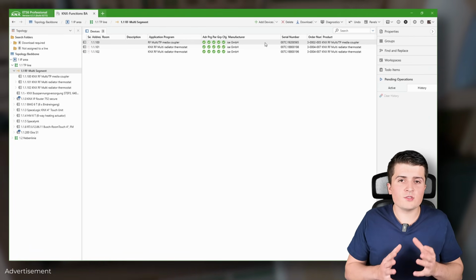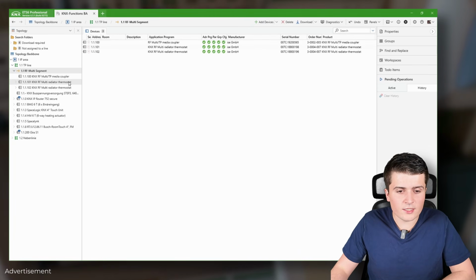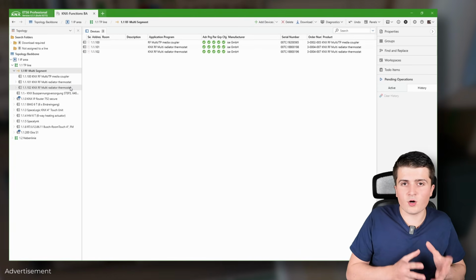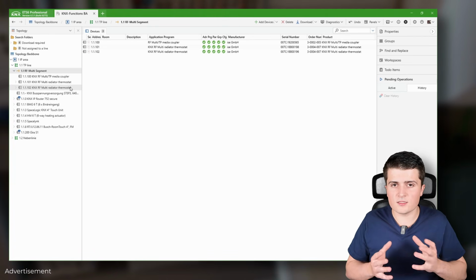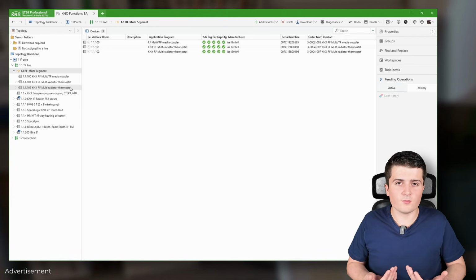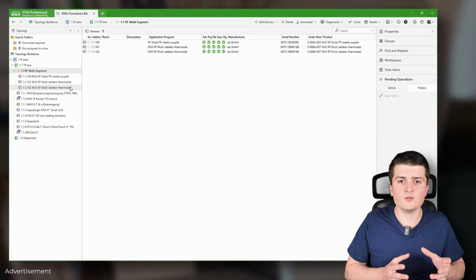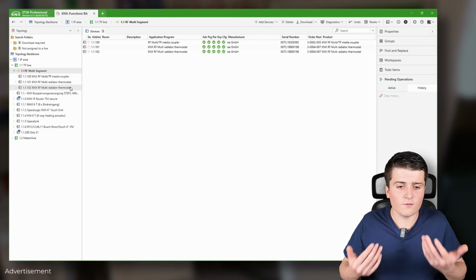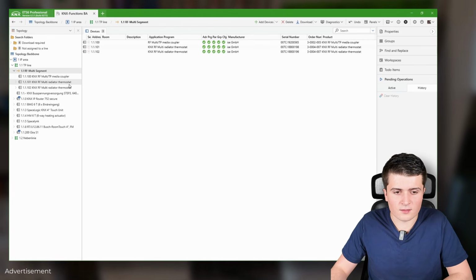And so therefore I want to have the following, or I have the following situation. Those two radiator thermostats are both in one room. One of those radiator thermostats shall be the master device with the thermostat controller, and the other one should simply use the commanding value of the first controller. So let us parameterize that.